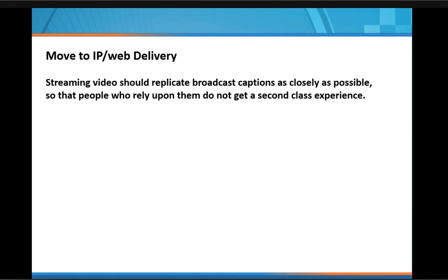That's the intention. Whereas 708 can also carry more languages than 608 can. So for example, 708 might carry a track that's in Chinese or Japanese or Korean, things that you cannot do in 608 because it doesn't support those, and obviously those wouldn't exist in the backwards compatibility bytes. But for your primary language, English, it will be carried both in 608 and 708 in the same stream.